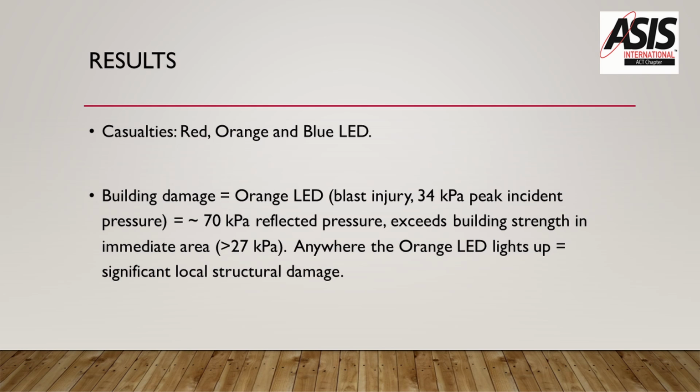So we can place the receivers around to see where would the lethal danger radius be, where would the injury dangerous radius be. But also importantly, we say, what's on the other side of that wall? And the answer is it's the computer center, or it's the boardroom, or it's the kids' crèche, or whatever it might be. Fine, we can suggest graphically now that if 5 kilograms explodes here, that part of the wall will fail. And whatever's on the other side of that wall will be severely damaged. So we actually have a visual, real-time, real-world indication of the results.